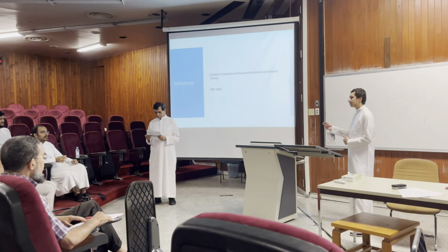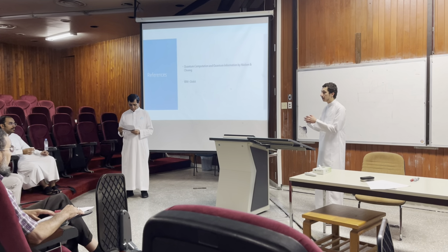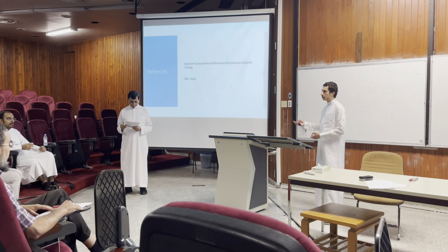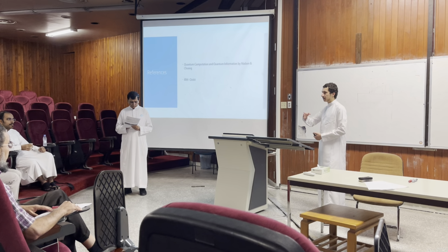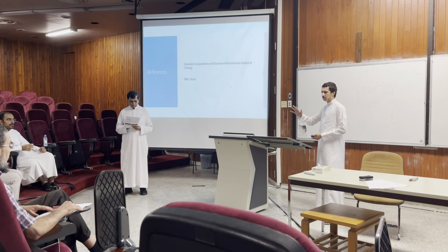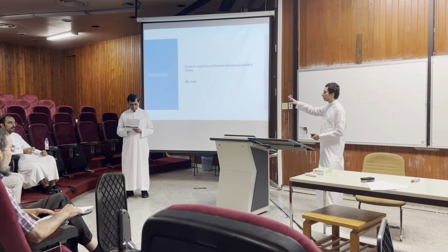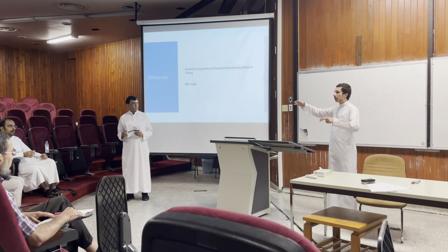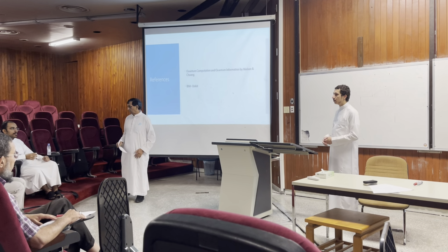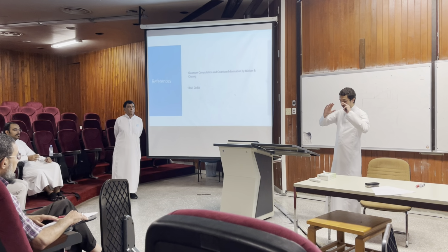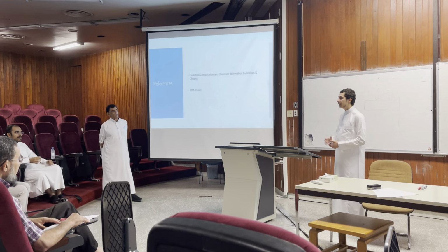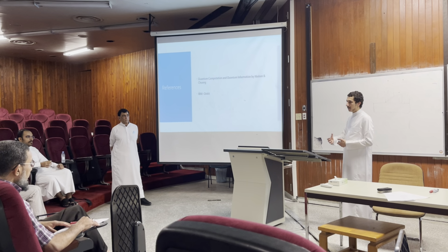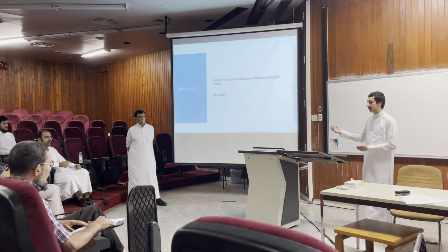Well, in the context of quantum computing, when we want to implement it on hardware, usually all we need is a Josephson junction. Typically what we do is we use niobium because it has a higher critical temperature, maybe 10 to 15 Kelvin. And usually we operate the quantum computers at millikelvin scales, so it's far away from the critical temperature. So we don't really need to dive deep into the theory of superconductivity. The basics that we get of just a simple Josephson junction, that's more than enough for our application here.